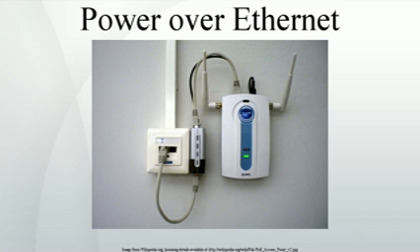The additional heat generated in the wires by PoE at this current level, 4.4 watts per 100 meter cable, limits the total number of cables in a bundle to be 100 cables at 45 °C, according to the TIA. This can be somewhat alleviated by the use of Category 6 cable which uses 23 AWG conductors.